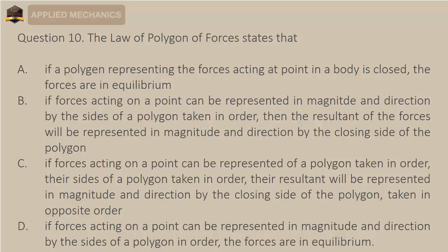C. If forces acting on a point can be represented by the sides of a polygon taken in order, their resultant will be represented in magnitude and direction by the closing side of the polygon, taken in opposite order. D. If forces acting on a point can be represented in magnitude and direction by the sides of a polygon in order, the forces are in equilibrium.